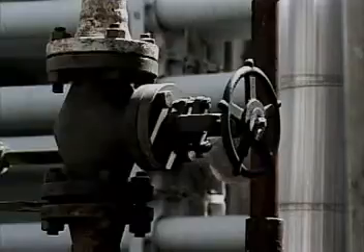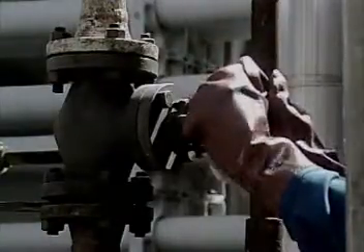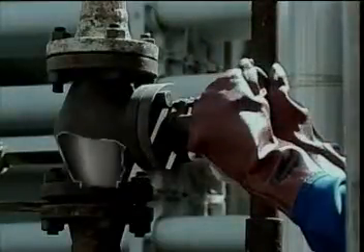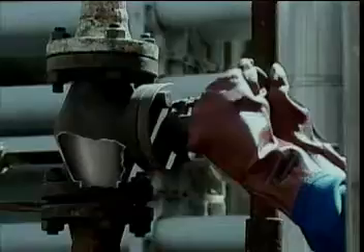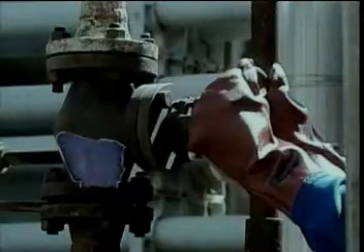Energy transfers and energy conversions occur continuously in fluid systems. Sometimes these energy conversions are enormous. For that reason, there are some precautions associated with fluid system operation. For example, it's important that flow control valves in a liquid system be properly adjusted to prevent changing flow through the system too rapidly. The energy conversion from a rapid flow change can create a pressure pulse that travels through the entire system.